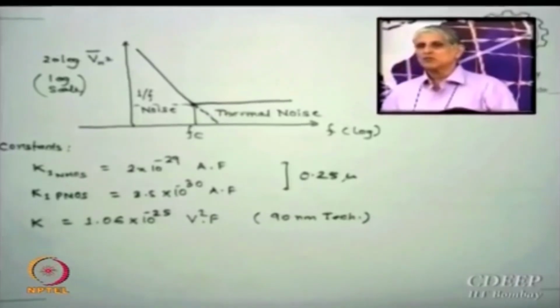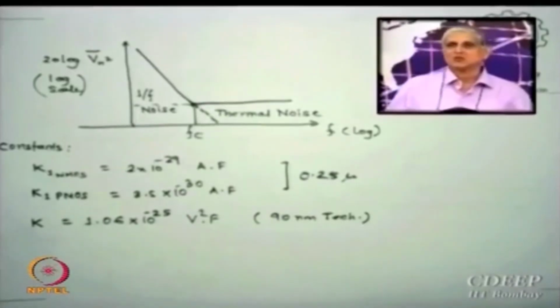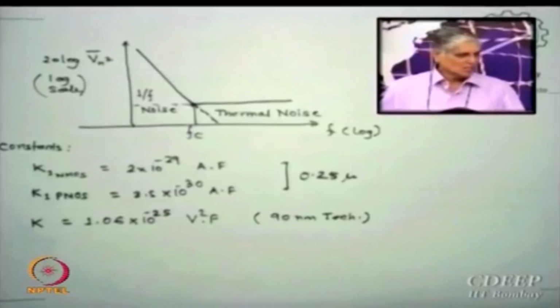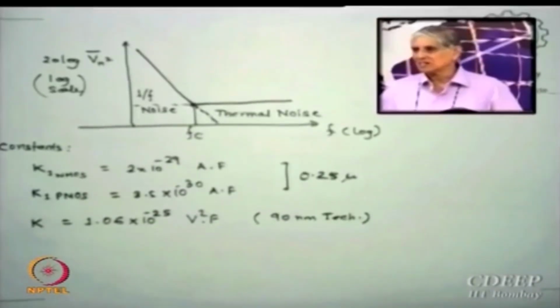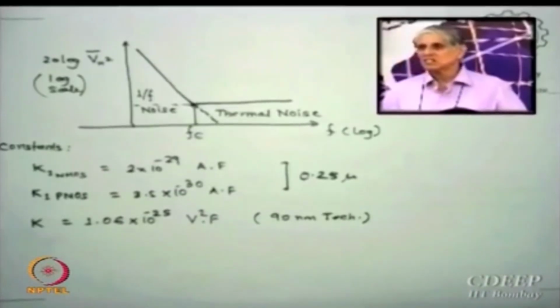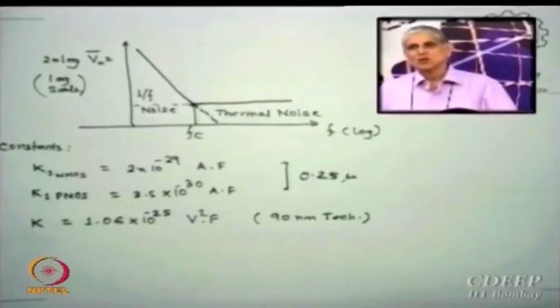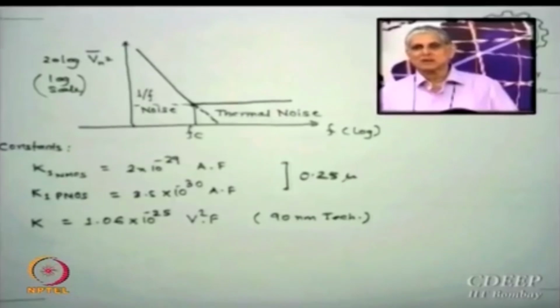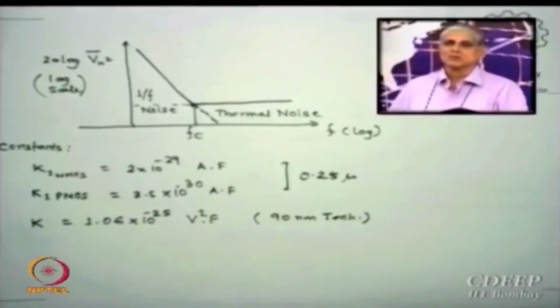We figured out the first hit was our noise itself, because it was just increasing and increasing as the nodes started going down. Okay. You can also see the term L square in the denominator there. Is that clear? So the smaller the channel length you use, the larger the noise you create. Is that clear to you? So some issue has to be understood, that why I am talking so much about it, because you have already gone to the 22 nanometer process.